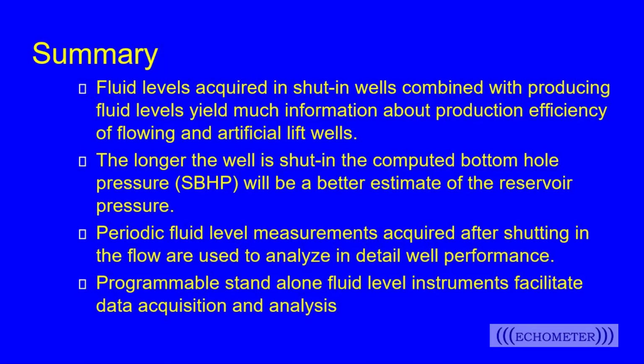In the future, we're going to talk about pressure transient testing. Even if we don't get to the point where we're truly stabilized, where it's reached the maximum pressure it's ever going to reach, the static bottom hole pressure, as long as we reach, say, a pseudo radial flow infinite acting portion of that buildup, and I know that's a mouthful, and we're going to simplify that when we talk about pressure transient testing, we can extrapolate what that pressure will build up to, a number called P star, an extrapolated reservoir pressure.